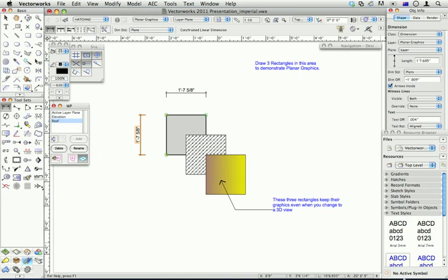Now, text styles can also be dragged and dropped on dimensions. So you see one text style is different from the other. One's slightly bigger than the other. So you can assign a text style to your dimension standard, and now you've got global control of all of your text, your dimensions and your blocks of text and callouts through this concept of text styles.